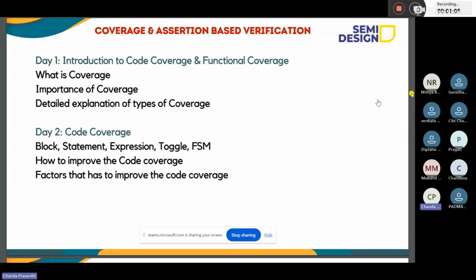And how, at SoC level or IP level, whether in SystemVerilog or UVM verification, the coverage analysis can be done, and what steps we need to follow to get the coverage report, like how many bins are hit, how many holes there are, and what percentage of coverage we got from the analysis. All these things we are going to discuss on day one.